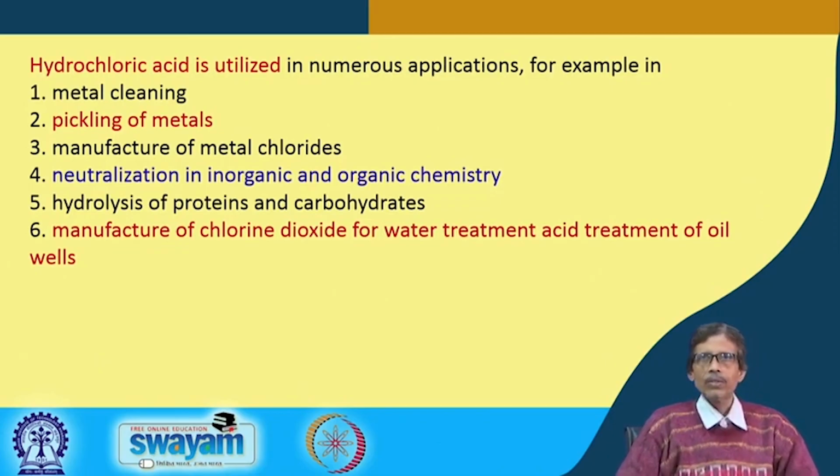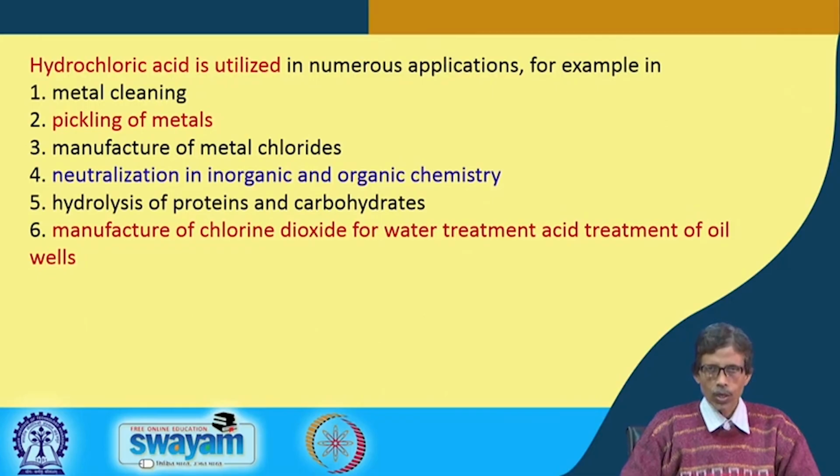So if a metal surface is covered with hydroxide, oxide or chloride, we can treat it with hydrochloric acid. Even if the solubility of the already present carbonate or chloride is not very high, the fresh addition of hydrochloric acid will clean it as the corresponding metal salt from the surface, such that we get a very shiny, very clean surface, which we require in most cases when we use it directly in industry. We will see this afterwards when we talk about the industry producing high grade metal and high grade silicon, which are in huge demand.